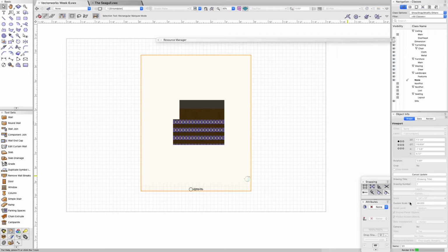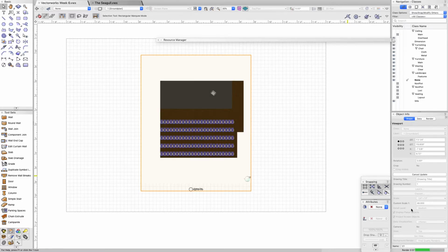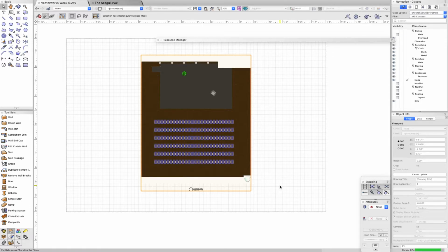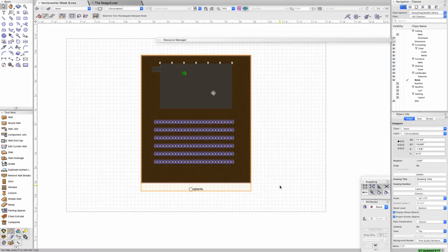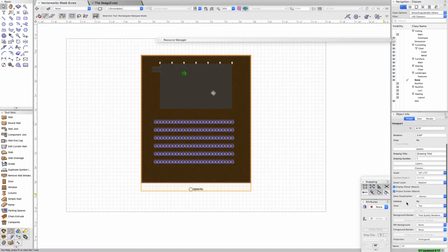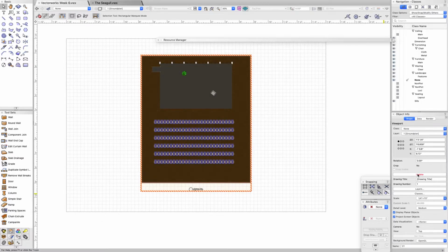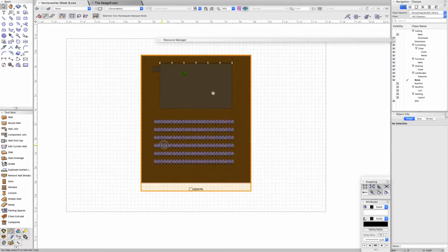And it does this so that if you're clicking through rendering options, it doesn't try to re-render this too many times. You'll see the little teapot that says it's loading. This is going to take a minute because this is final quality Renderworks, and there's quite a bit of stuff here. So now that I've done this, I'm going to change it to OpenGL just because that'll render a little bit faster. But again, it's just going to do a little box. I hit update. And there we go. So OpenGL is a lot faster.